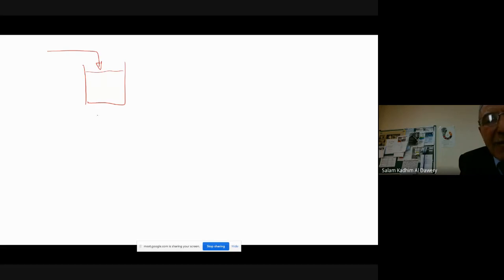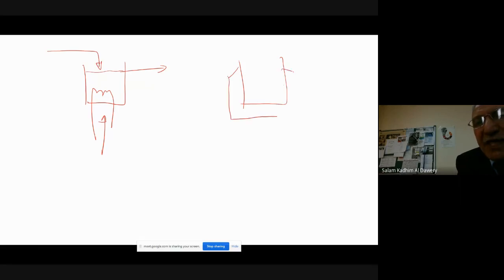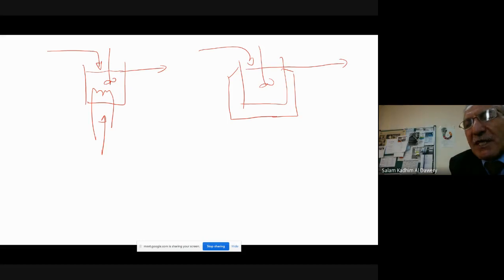We heat it either by a coil, using a heater, and this is the output, or by a jacket. Heating by a jacket is the same. This is on the mixing tank, same as a heat exchanger. So for heating, we've got steam, and here it is condensed, similar to the reflux drum. Before the reflux drum, there is a heat exchanger for that particular purpose.